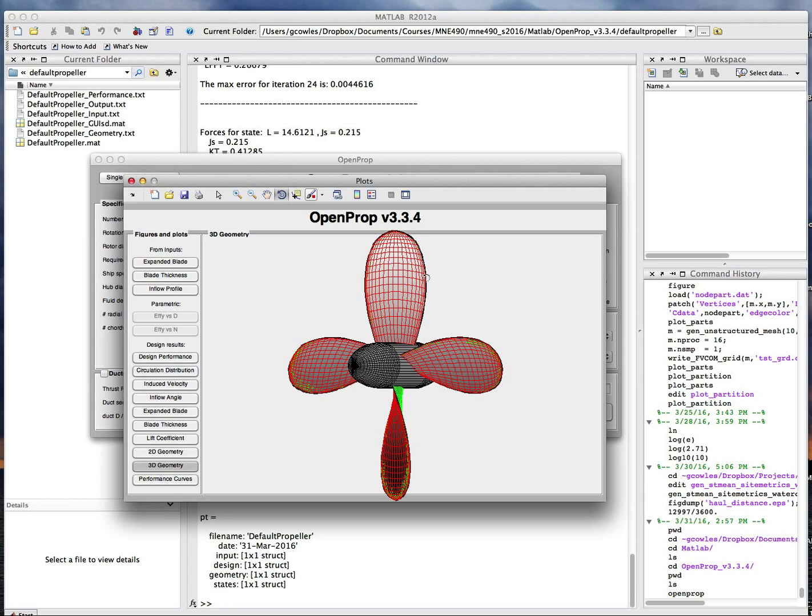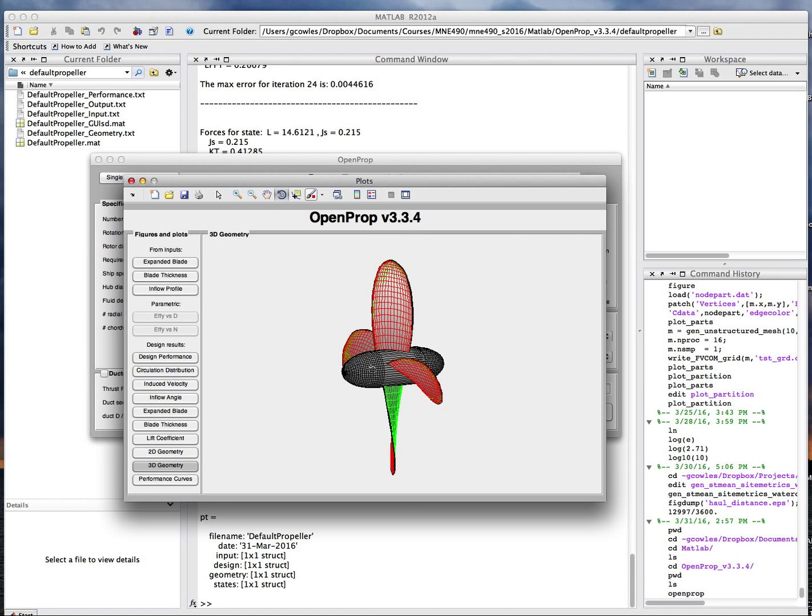Now this distribution of area, expanded area, comes from the chord, which is again the expanded value. It's the curve value that you set, or that is what came preset in the geometry menu. That was the root value, or the value at like 20%, 30%, 40%, 50%. It was thickest around here, and then decreased to 0.001 up here as a fraction of diameter. And it puts in some kind of standard hub here. And again, this hub diameter was part of our input.